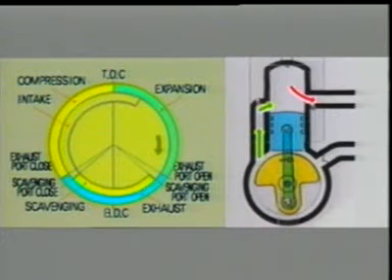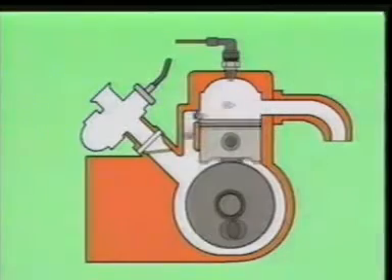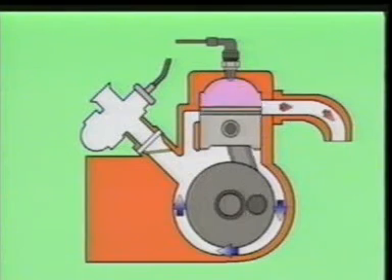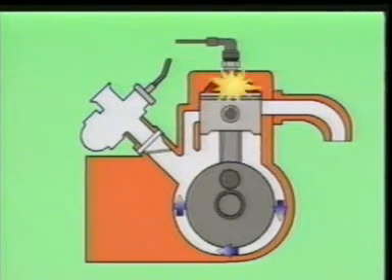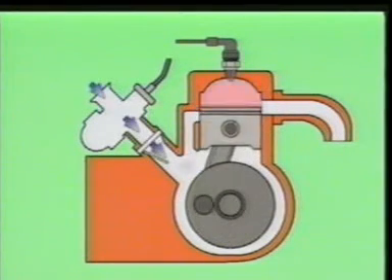Then, as the piston head passes the scavenger port, opening it, the mixture of the primary compression in the crankcase chamber is injected into the upper cylinder chamber by the scavenging effect. The operation of the two-stroke engine is the continuous repetition of this cycle.